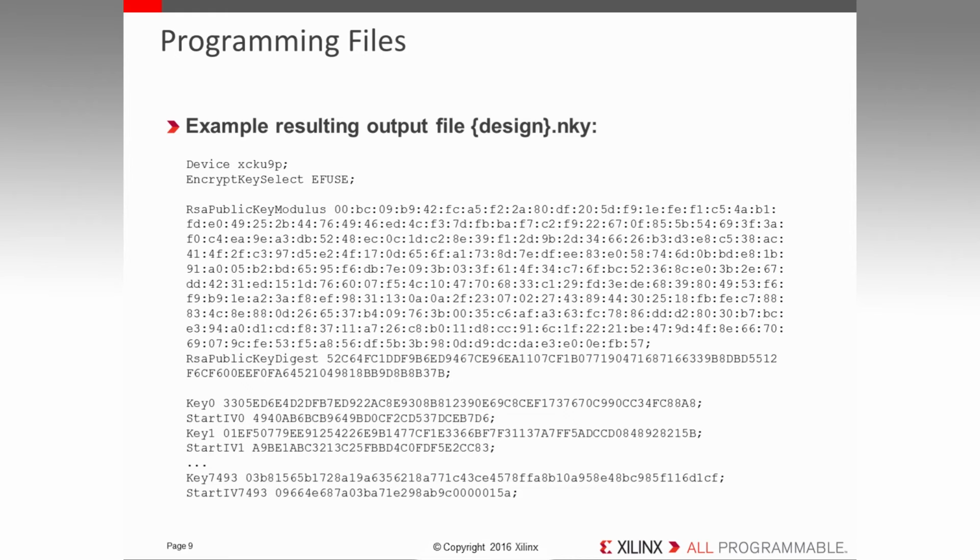If you didn't provide enough encryption keys in your input NKY file for the requested key rolling block size, you'll find the additional keys generated by Vivado in this file. I abridged this for presentation because it contains more than 7,000 encryption keys. The first 2 are from me, and the rest were generated for me by Vivado.